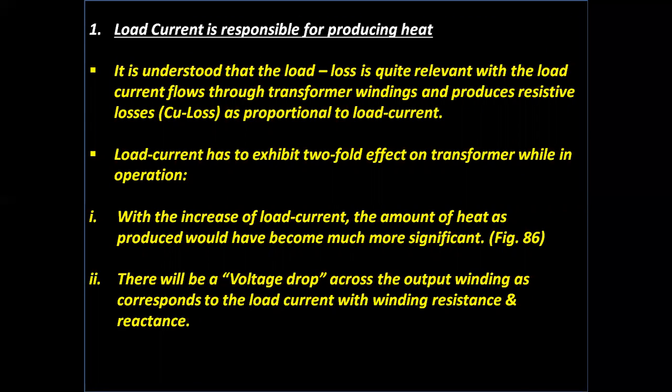It is understood that the load loss is quite relevant to the load current flowing through the transformer windings and produces resistive losses, that is copper loss, proportional to load current. Load current exhibits a twofold effect on the transformer while in operation. One, with the increase of load current, the amount of heat produced becomes much more significant.